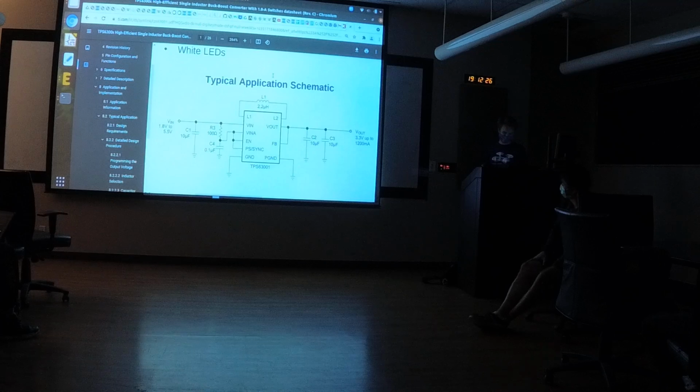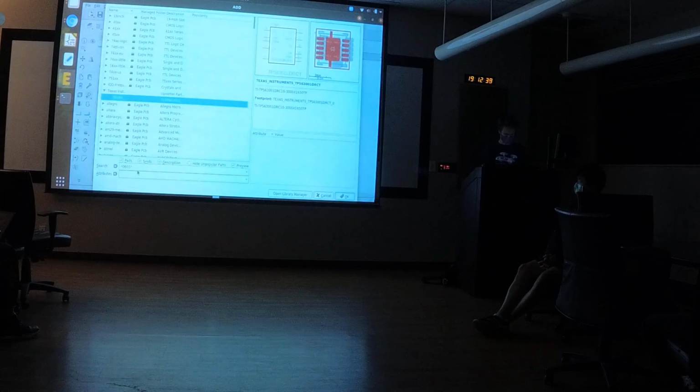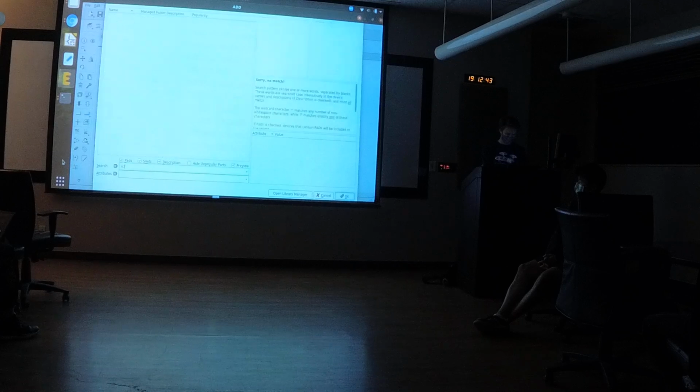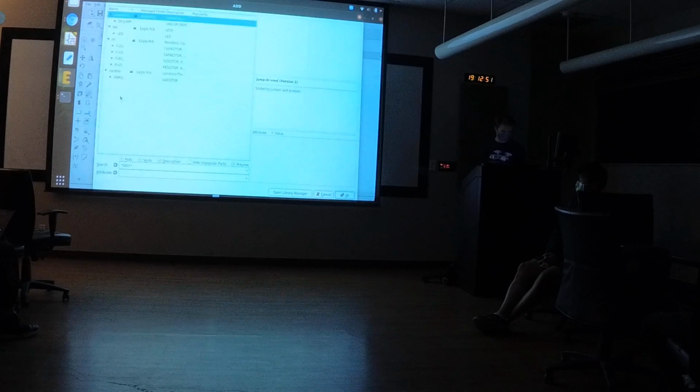Yeah, so let's see, what's the first thing you see? L1 and L2 are connected to a 2.2 microhenry inductor. This is the symbol for an inductor. So we're going to go add, okay? Can you search RCL? No, you can't. When in doubt, just use asterisk. Yeah, asterisk.